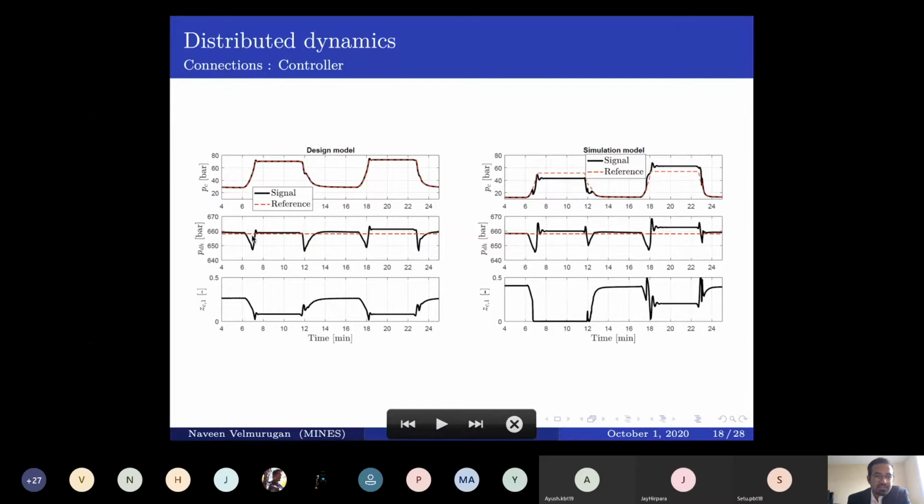That is all given. So from that, and using the ODE model, the controller calculates, okay, if I have to maintain this, I'm going to maintain such pressure at the choke side. And then it also calculates that to maintain this particular pressure, I need to change my choke opening accordingly, right? So that's what it does. It wants to track the pressure and accordingly tries to change the choke opening. And you can see at some points the pressure drops and it cannot maintain the particular value. But it's definitely much better than a manual operation.